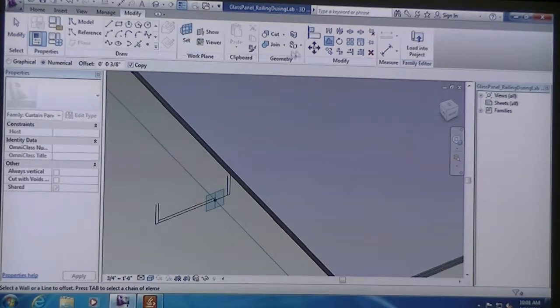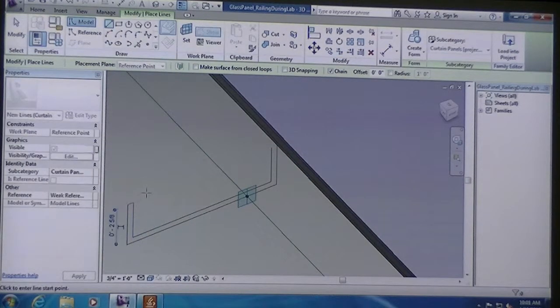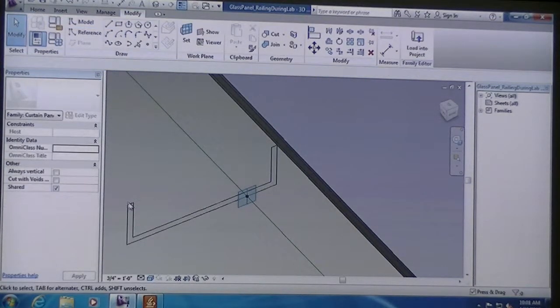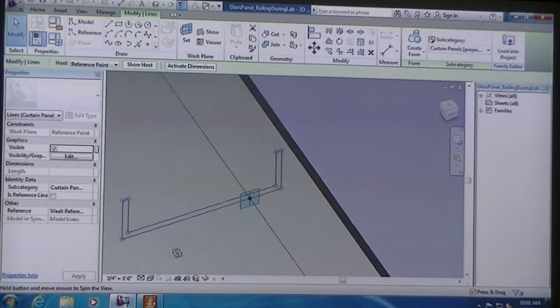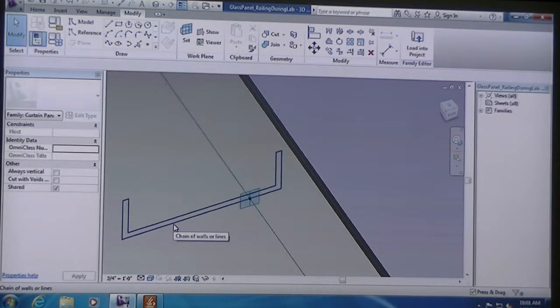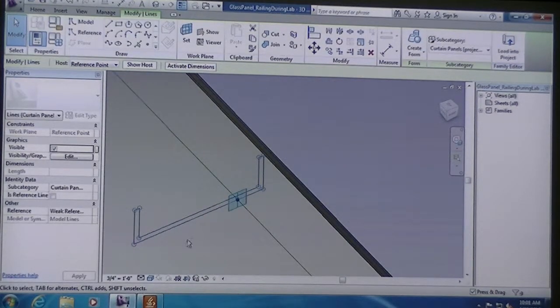of each of these. And then I need to do my trim and extend, because we have to make sure that we have a closed shape. And then at the top here, I'm going to close off the C channel. You have to make sure you're snapping each time, and if it's properly closed at the end, you should be able to just highlight or hover over this component and the whole entire profile shows up, or it gets selected.